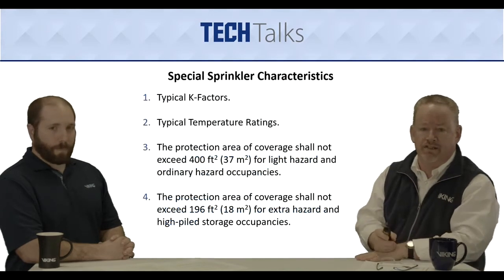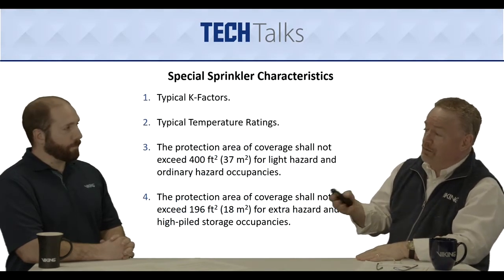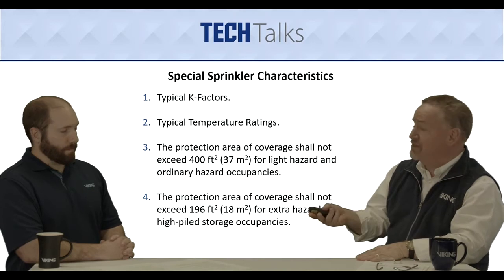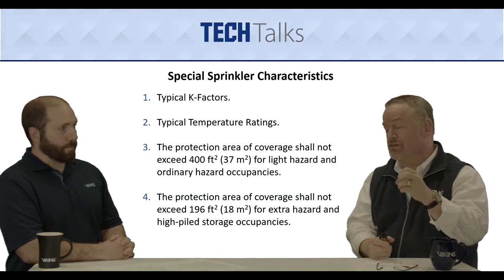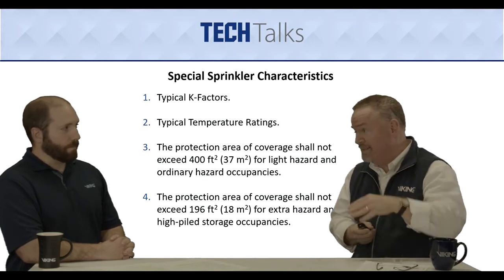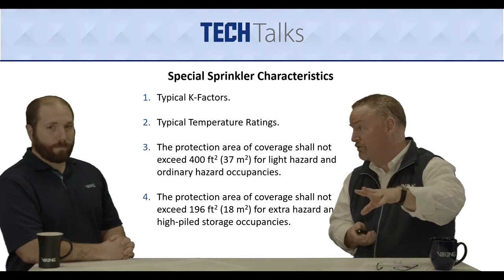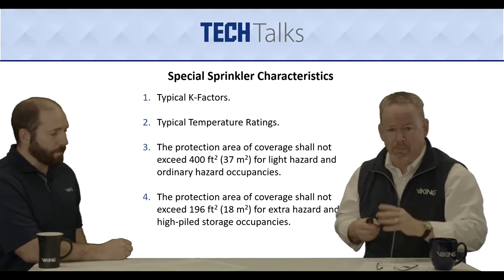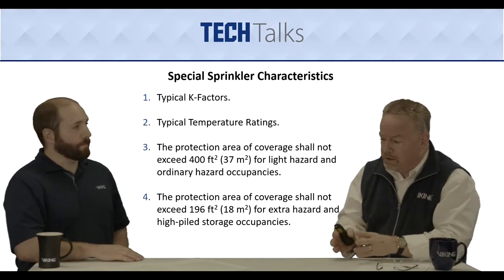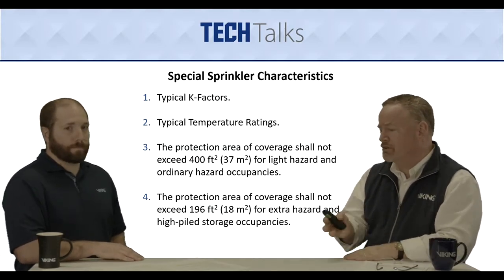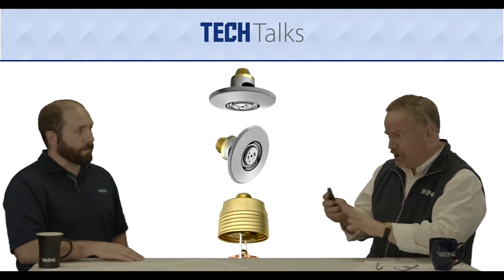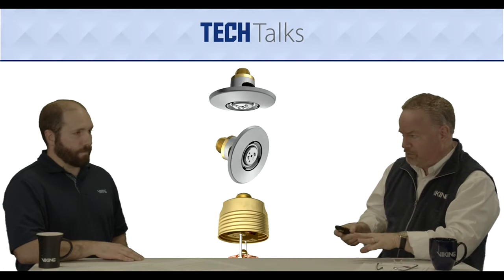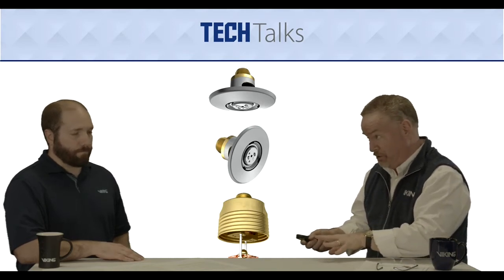There are certain things here that we can't mess around with. We go with typical K factors, typical temperature ratings, and typical areas of coverage, depending on what we're going for. So what I wanted to talk to you about is, we've listed three special sprinklers that we're going to talk about today, but let's start off with what's not a special sprinkler and maybe why it's not a special sprinkler.